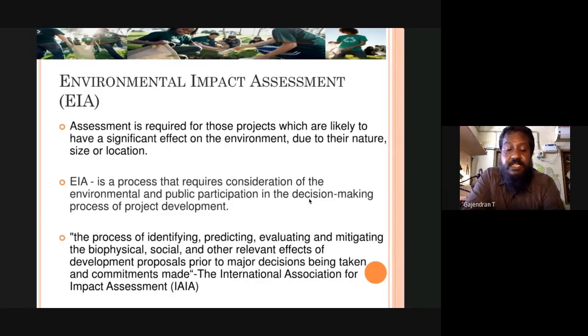The reason why I said this is high-rise developments, the big commercial developments. These are projects which are going to use a very large quantity of water. So what they do is they try to exploit by drilling bores, and they'll definitely reduce the water table. So many bores will be taken up that the water table in that particular region would have a major impact from one development itself. Otherwise, there could be a water source like a lake somewhere close by, and they can exhaust the whole resource of it.